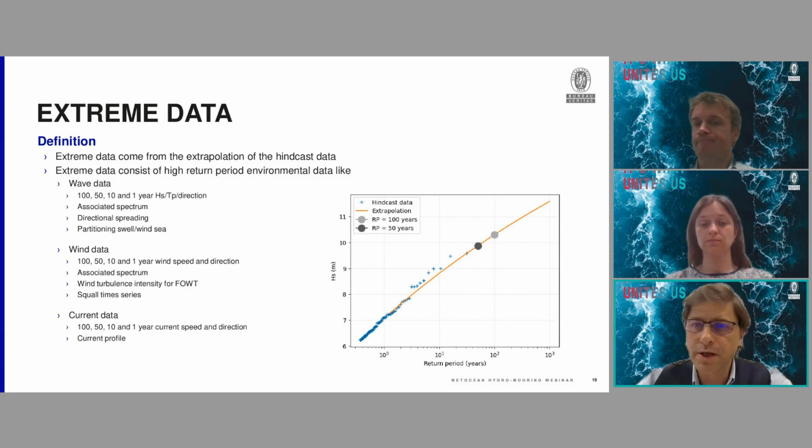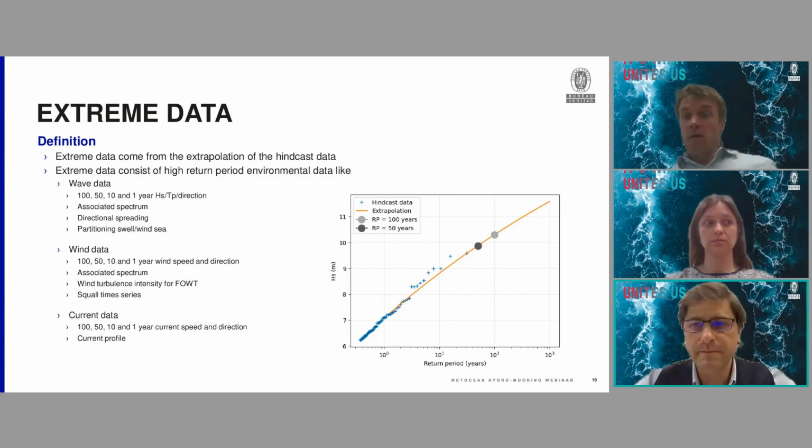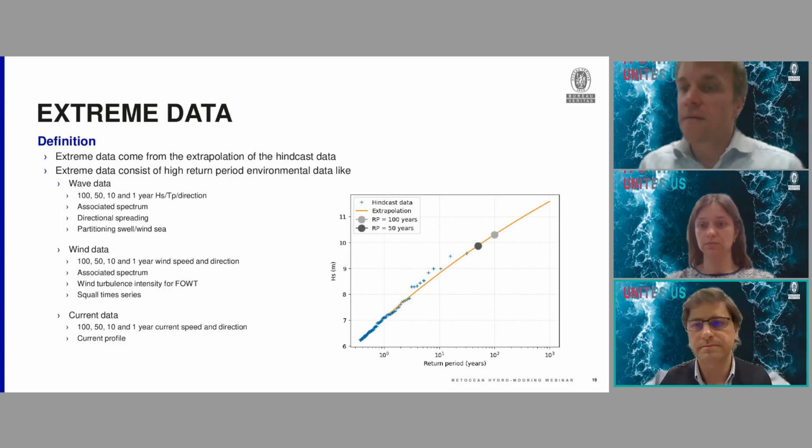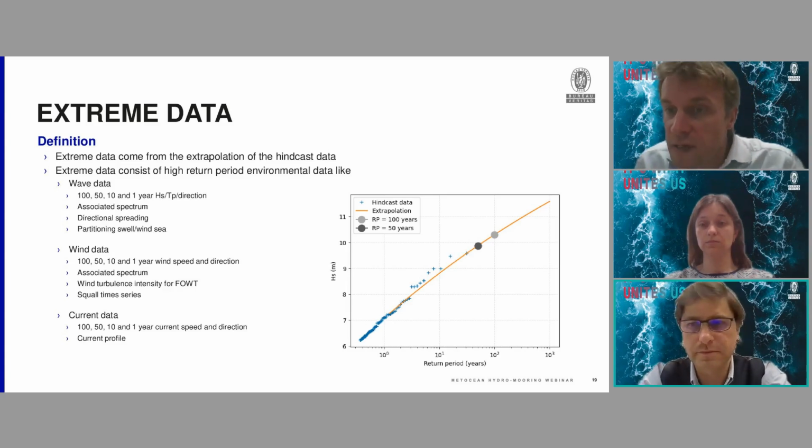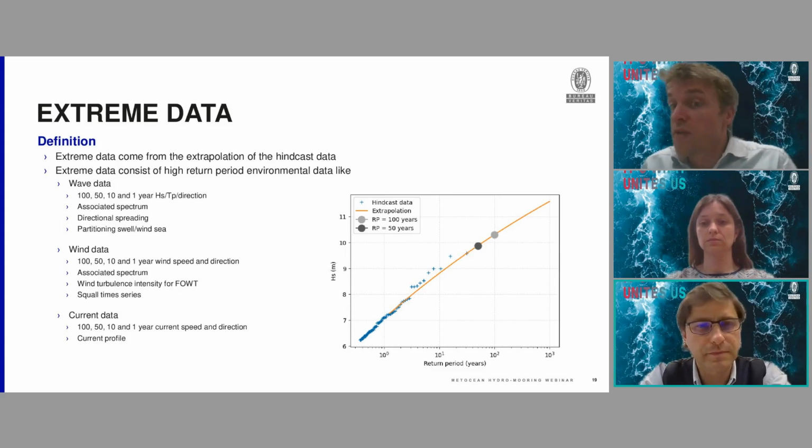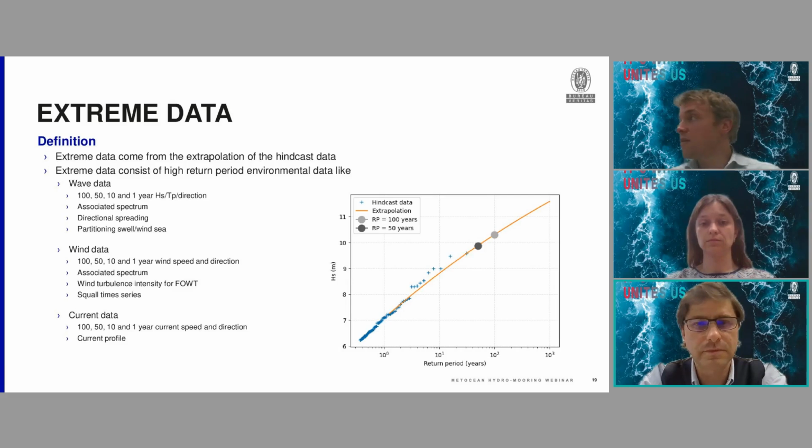Okay, and I have one last question for you, Guillaume, once again regarding the software. How is the nonlinear behavior of the mooring lines modeled? So if I read fully the question, it asks if Hydrostar can include this. Now in frequency domain, we cannot include the nonlinearity of the mooring system. In frequency domain, what we can have is only a linearized mooring, which is generally not sufficient for actual mooring lines.